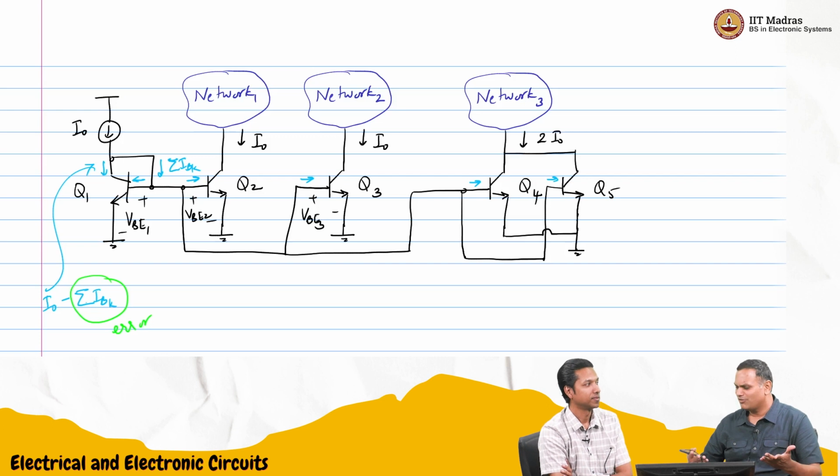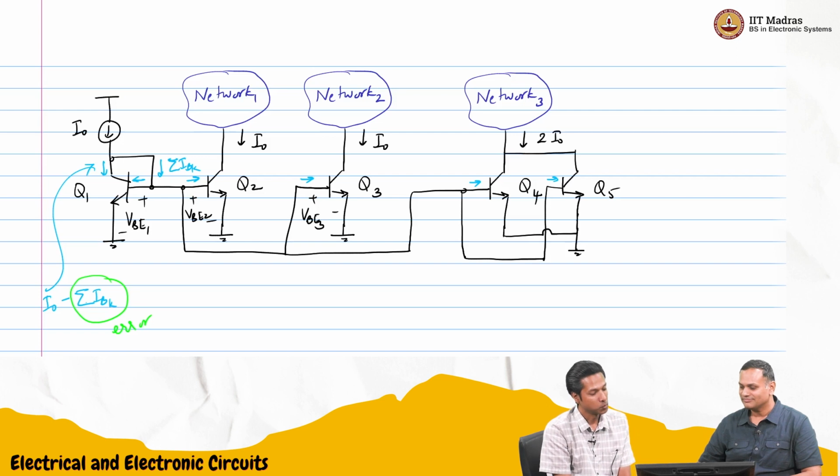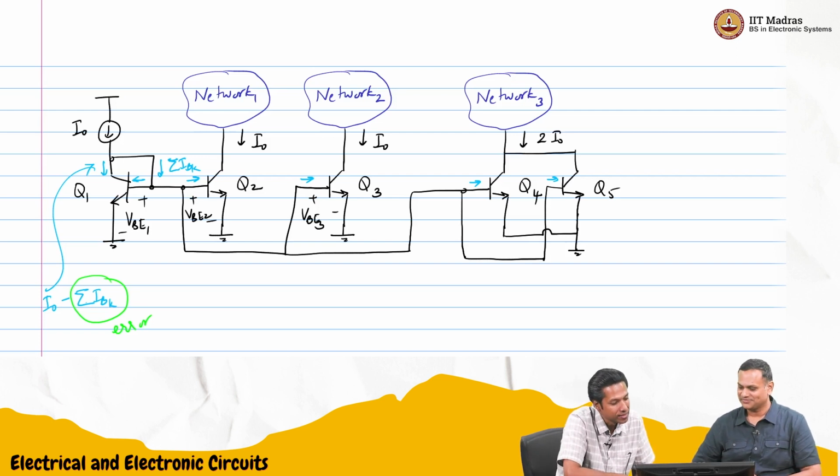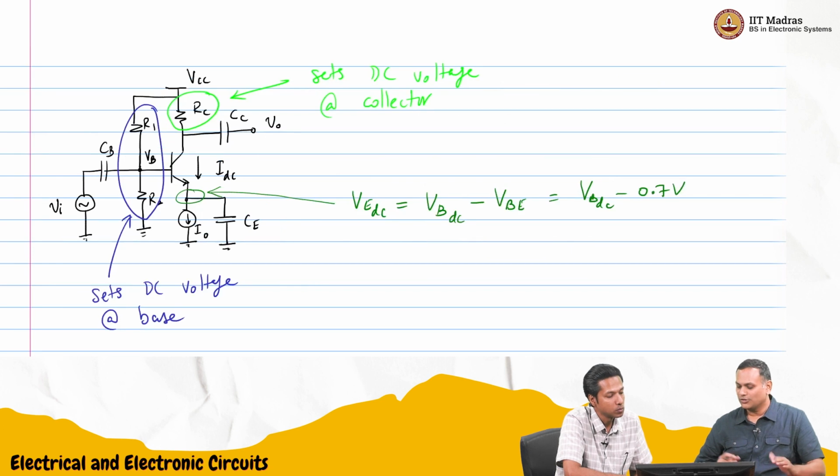For normal circuits, you can easily use this to bias your amplifier. And even if there is an error, it's a fixed error. It's a systematic one. So now we even know how to design this current source also.